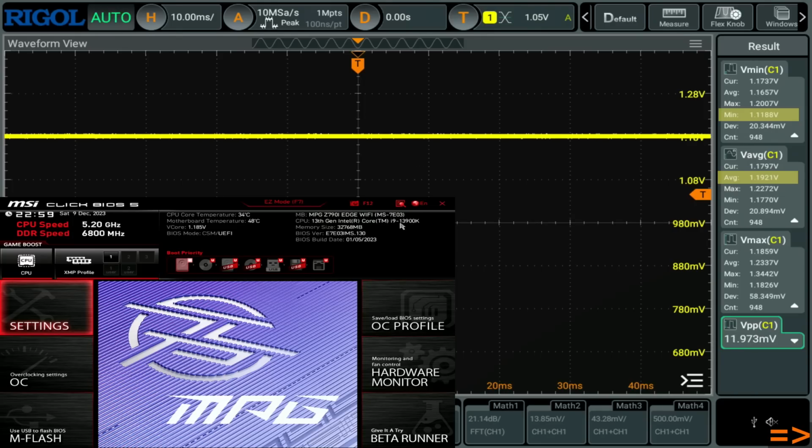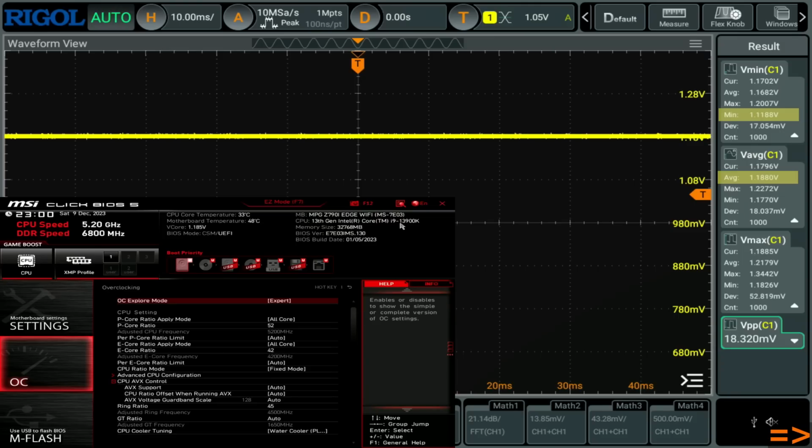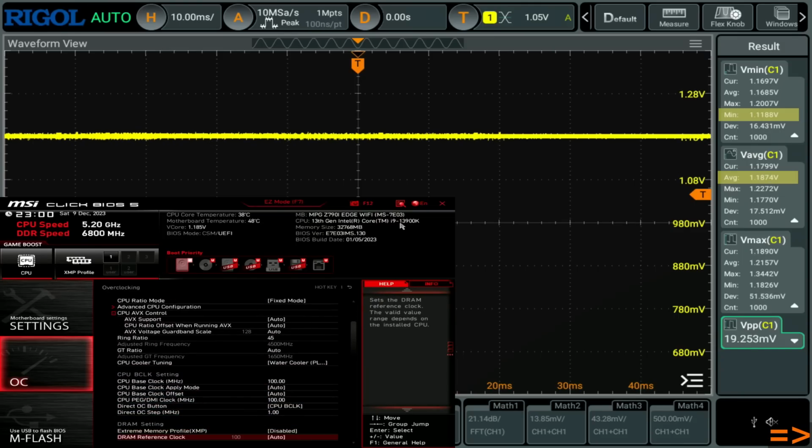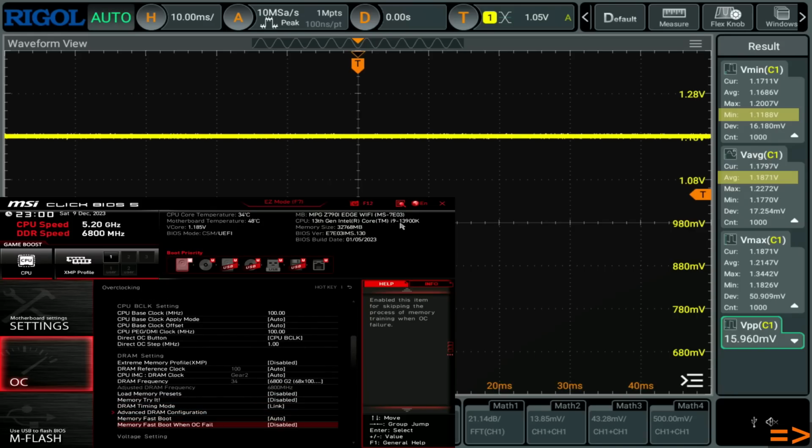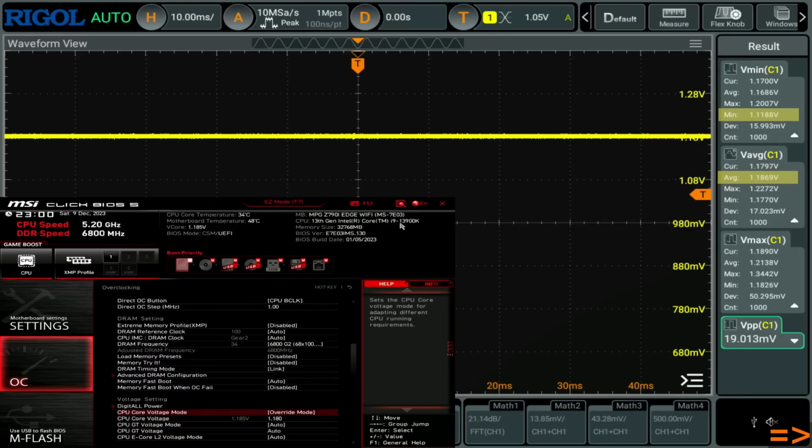which is the usual core voltage sensor that you see in CPU-Z or the Vcore sensor that you have in HWiNFO, is normally hooked to some kind of random location somewhere on this Vcore power plane. So on some motherboards it reads really high or kind of close, or it's all over the place. So having a motherboard with this VR Vout sensor is actually really convenient if you're trying to judge how much V-droop the LLC setting actually has, because on the vast majority of motherboards, the Super I/O voltage reading is just unreliable. And there's really no way to know how unreliable it is without extensive extra testing that is annoying to do.